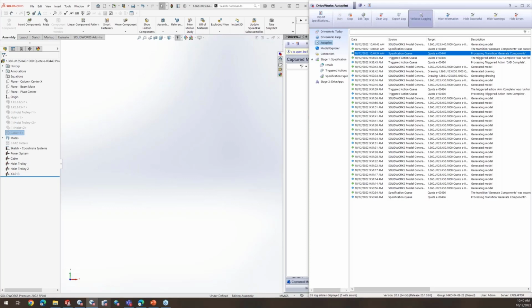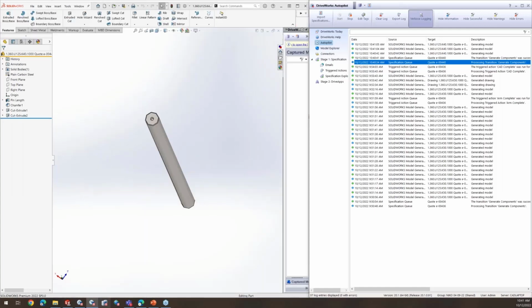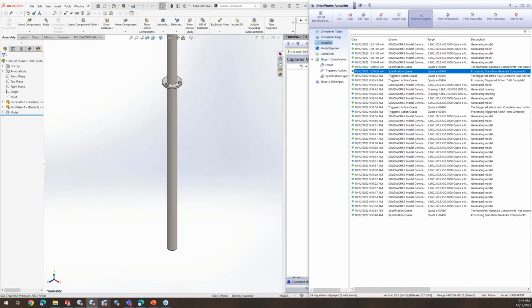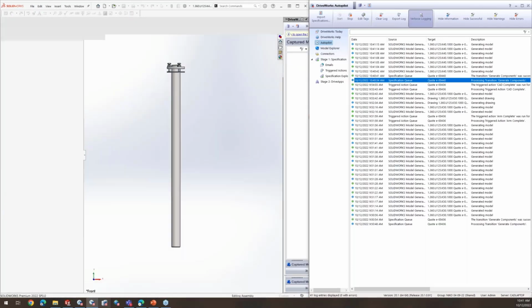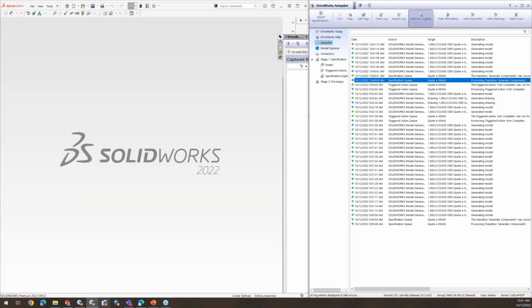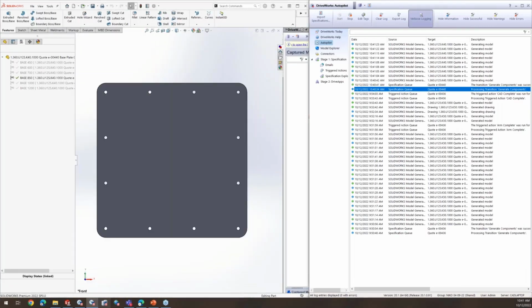There's various types of activity being done to this collection of SOLIDWORKS assemblies, sub-assemblies, part files, and drawings. For assembly, we can delete components, we can change component configurations, we can insert and mate new components on the fly. At a part level, we can interface with sketches by driving in drive dimensions. We can interface with part configurations. We can suppress unsuppressed features, and even drive advanced feature parameters.